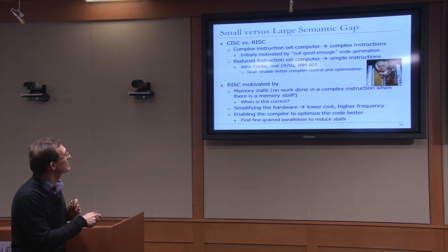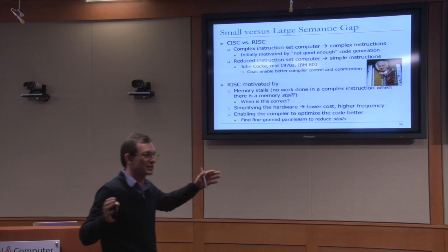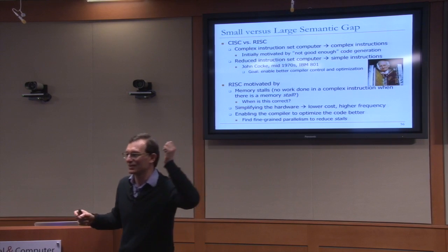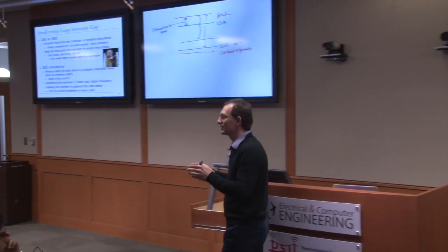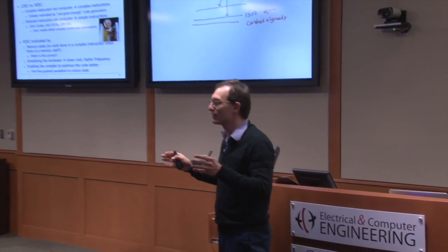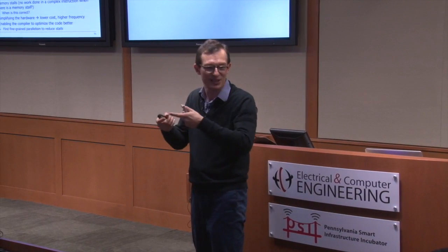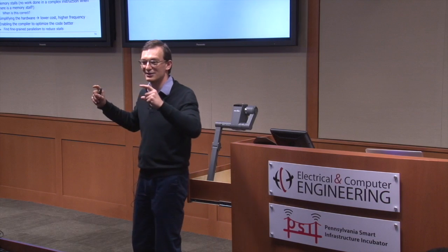And these big chunks of instructions were causing a lot of stalls. What does that mean? Let's say you have a string move operation. If it kept accessing memory, it would keep stalling. And there was no way to optimize the little operations that string move really does inside. For example, it increments the count register, right? There was no way to optimize that if you had a single instruction to deal with.